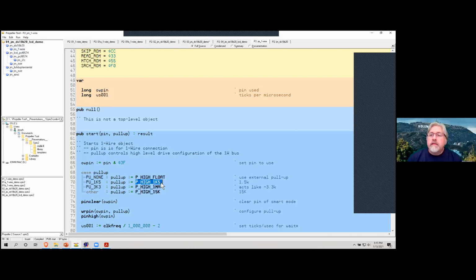Got it. That's why. And I have one of those. Remember when I was doing my iButtons, it said multi-key, but I wasn't sure what it meant. And then they have the temperature one, and the temperature one can be configured to take samples at a periodic rate, up to something like 8,000 temperatures. There are different size buttons for different numbers of samples, but you configure it and then it'll just take samples every X amount of time and store them, and then you can read out all those samples.